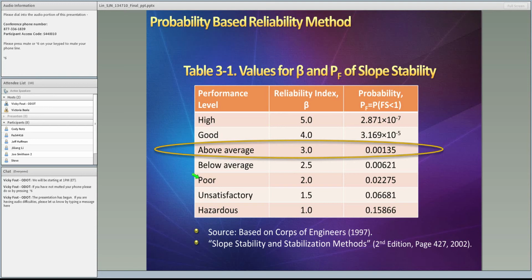And if the reliability index beta is less than the target, we have to choose a different shaft location and different spacing and diameter again to optimize the design parameters until it satisfies the target. And then we get the design result.